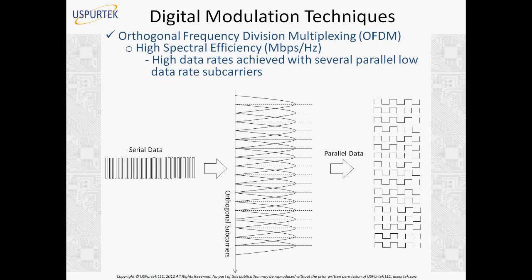So what we do here, we split this data rate into multiple subcarriers. So we have parallel data streams here which are much slower than the original. This was very high, it was 54 megabits per second. Now here it could be only 1 megabit per second and so on, or even less than that. So it's like having many parallel lines transmitting data. So parallel lines can carry more data actually. The data rate on each particular parallel line is much slower because that is the capacity.